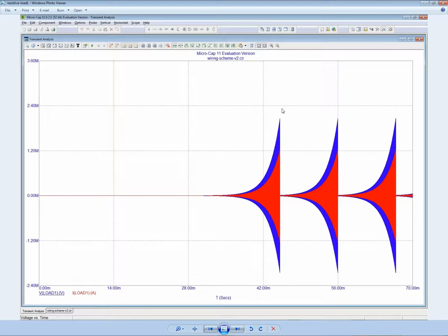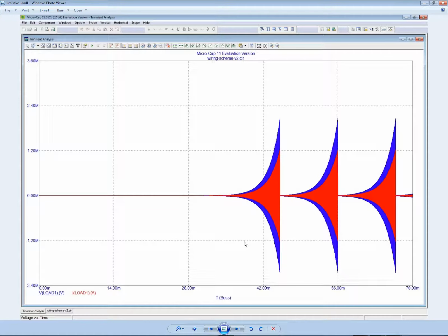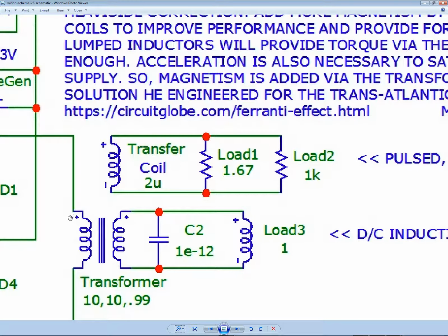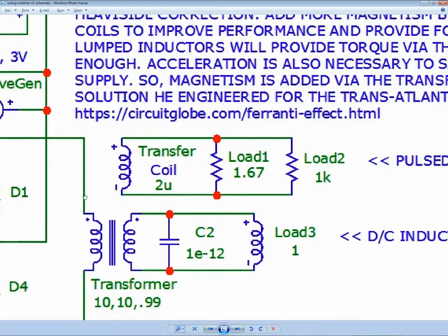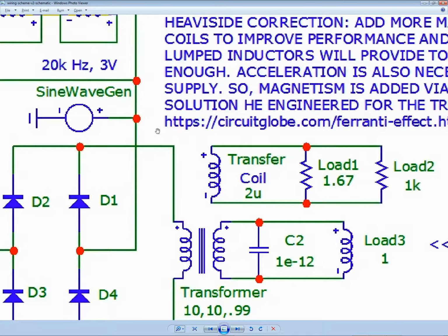And you get what I like to call staccato wedges, because if you did an in-depth view of this, let's see if I have that. Yeah. Then you see that the blue here, the voltage, and the red, the amperage, they're totally lined up, despite the fact that they're being fed by reactive power being transferred to this coil from these 4 coils here at a 10% coupling coefficient. So the coefficient of coupling is very poor. It's no different than a rotor inside of a single-phase induction motor, by the way.